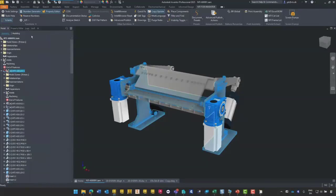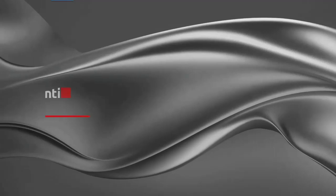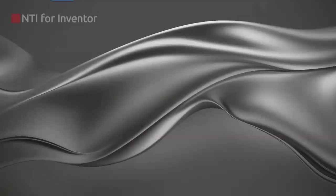And I'll just use an NTI function, open newest drawing. So if it is a newer drawing local, it will open that. And if it is newest in the vault, it will open that. So also a little function hidden in the NTI FOR INVENTOR.